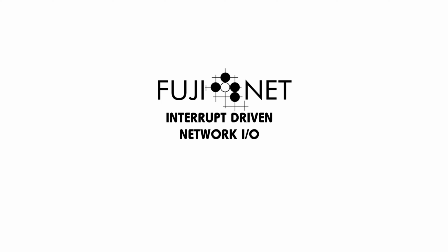This particular video shows that FujiNet actually has the interrupt and proceed lines connected to the SIO bus and to the ESP so that interrupt-driven network I/O is possible. This gives us a lot of advantages, but the biggest is that we don't have to keep storming the SIO bus with consistent status calls.